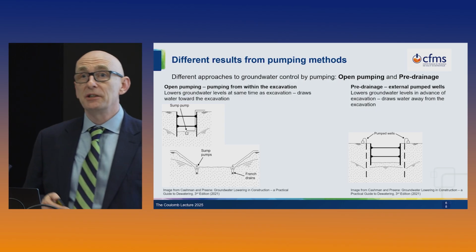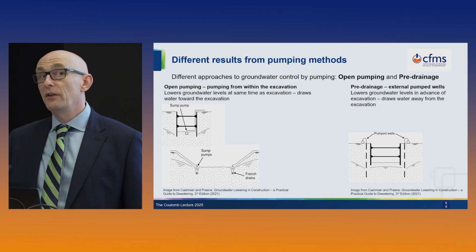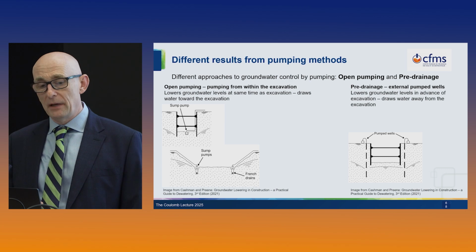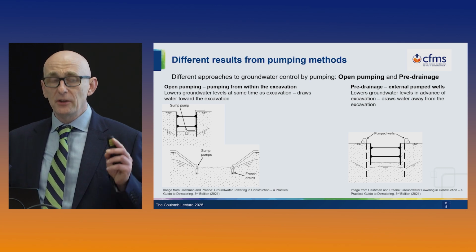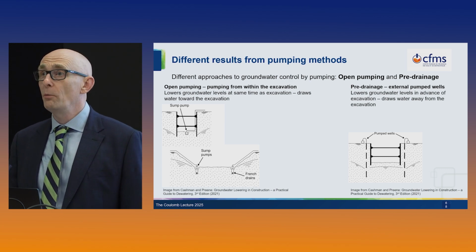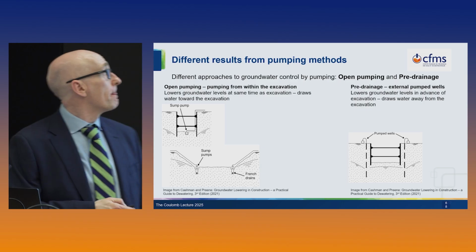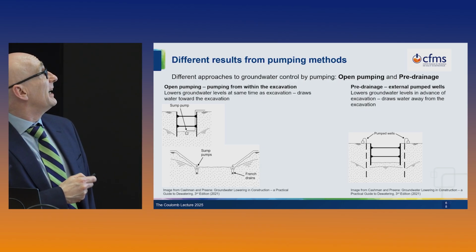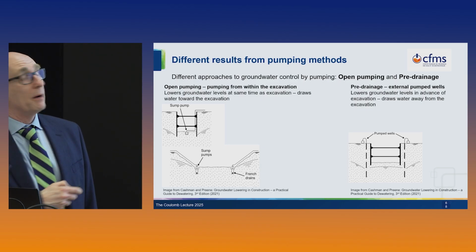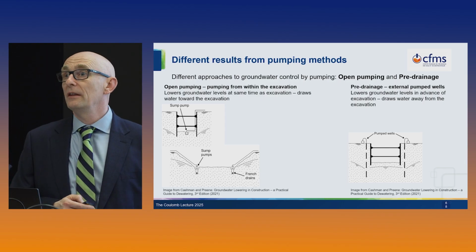And it's important to realise that you can get different results with apparently quite similar methods. So I'm going to talk about the pumping methods purely at the moment. I'm going to talk about the difference between open pumping and pre-drainage. Open pumping is shown here, and it's the simplest form of dewatering, where essentially we pump from within the excavation.